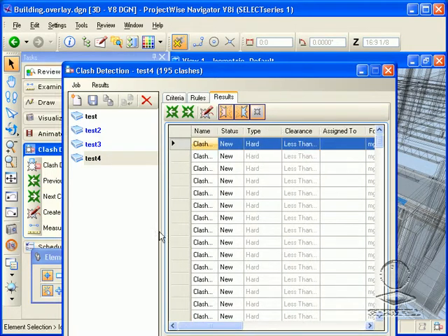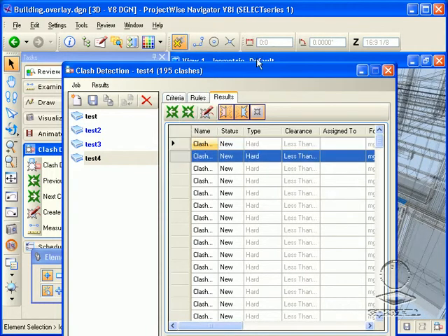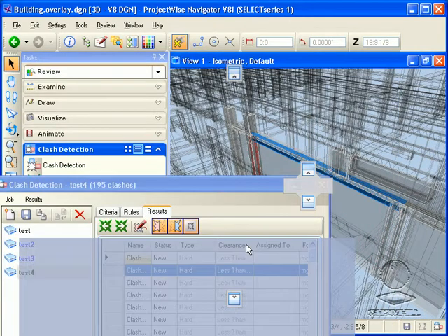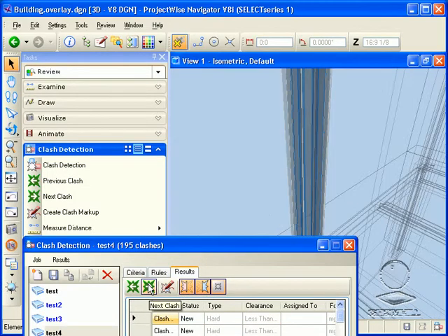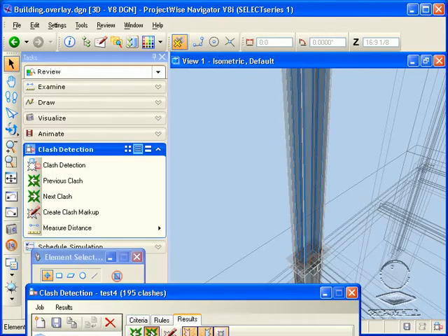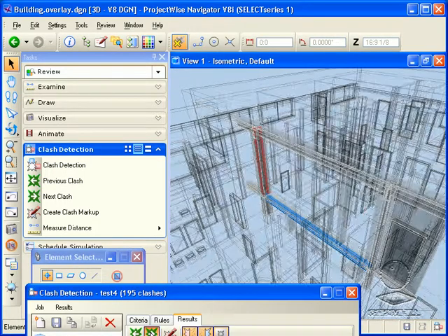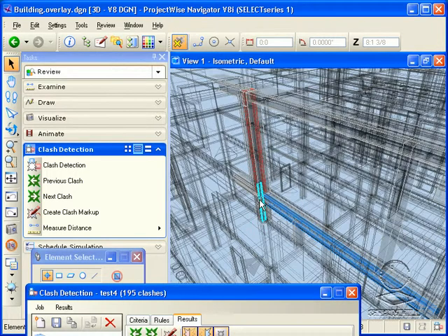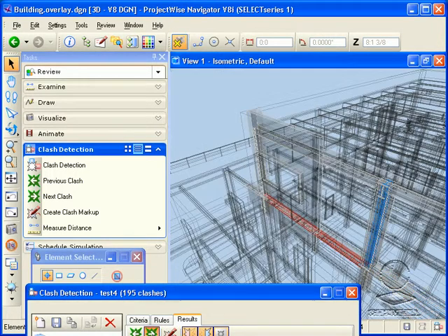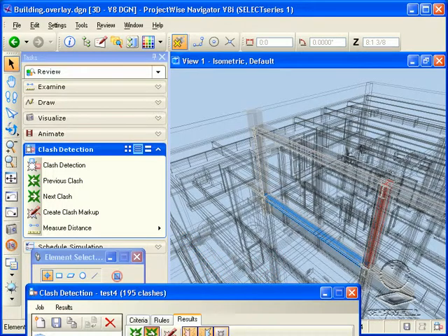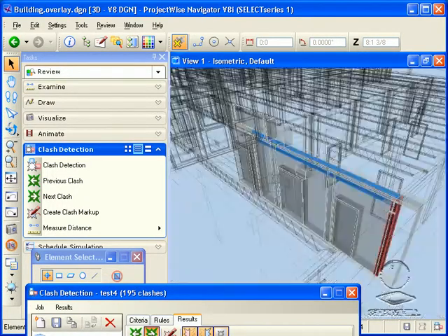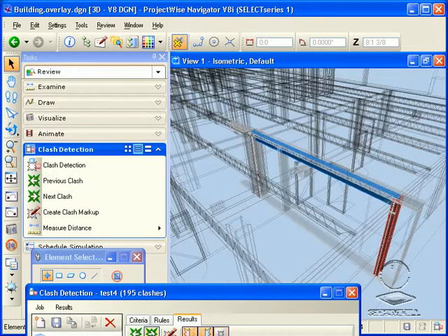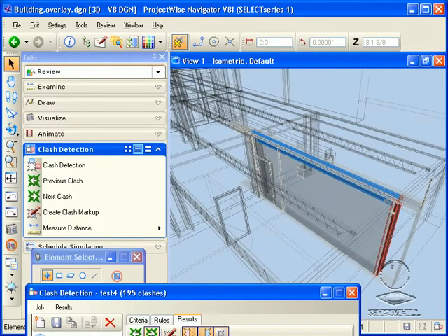So I did all the steel. So we'll go through, move this out of the way, and you can see by clicking on this next where there are any clashes with the steel. And some of these are just normal beam meeting column, and you can tell those. So you can scroll through and see for all the structure where things are clashing, and if it's actually a true clash or just an expected clash.